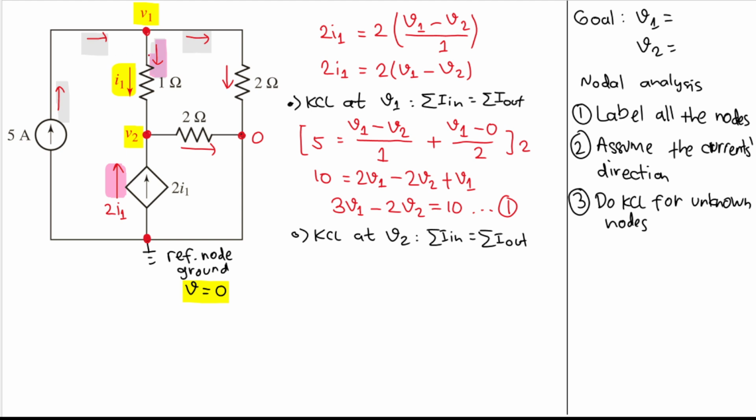So we will have this current here. The current comes from V1, and then the current goes to V2, so I will have minus V2. This is voltage, so we need to divide it by the resistance between them to get current 1. And then this current here, because this is a current source with the value of 2I1, we can just write plus 2I1, right?